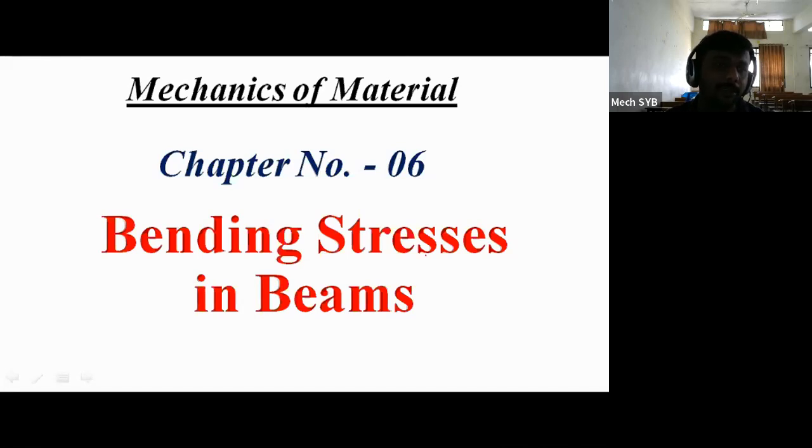simultaneously. We can apply the point load, we can apply the UDL, we can apply the UVL, we can apply the couple. So if a number of forces we are applying on the beam, then there is a possibility of bending, there is a possibility of shear force development. But why only calculation of the bending moment, it will not be sufficient to check the strength of the beam.